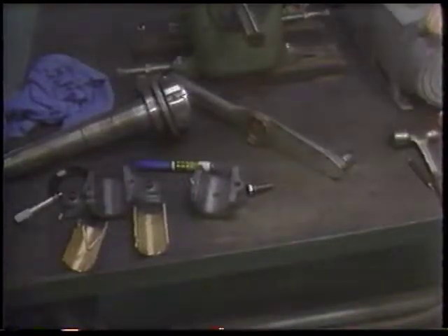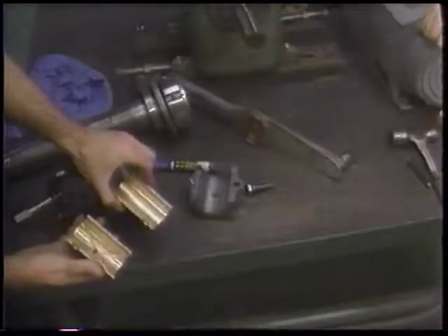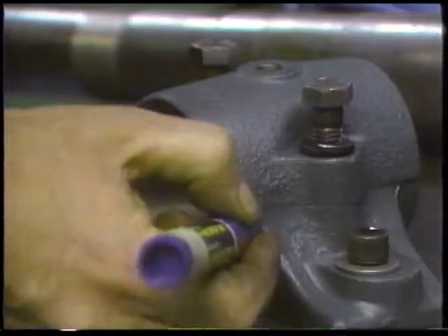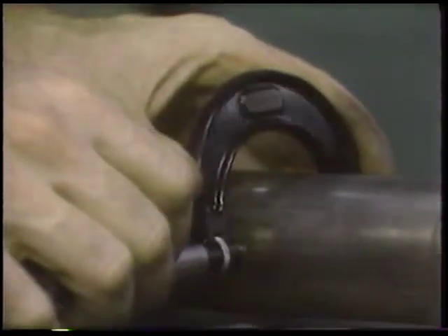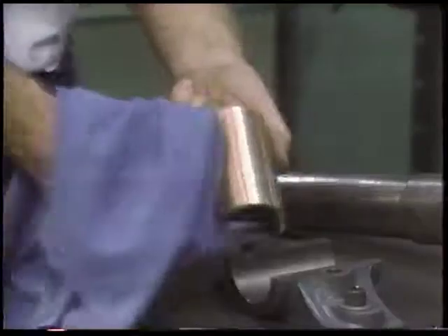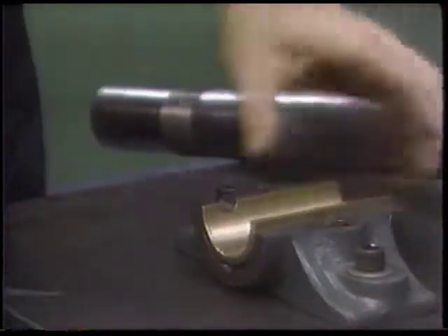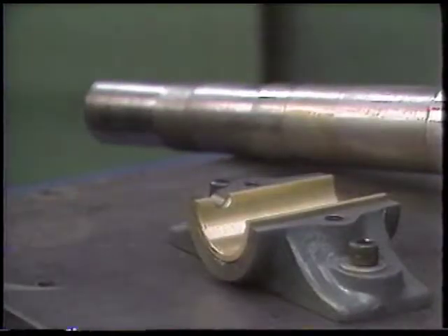Large plain bearings are often installed in half shells, like this. Installing these shells correctly is a precision operation. Initially, mark the housing in such a way that will allow you to reassemble correctly. Check the shaft or journal to ensure that it is not tapered, oval, scored, or rough. Always inspect and clean the back of the bearing and the mating surface in the housing carefully. Dirt under the bearing may reduce clearances and prevent adequate heat transfer.